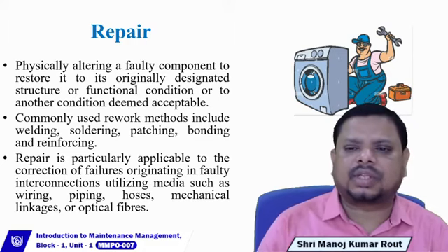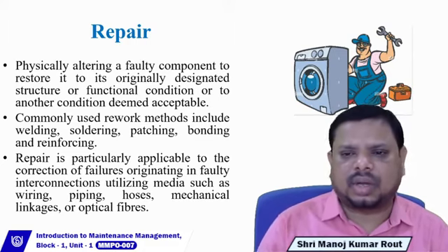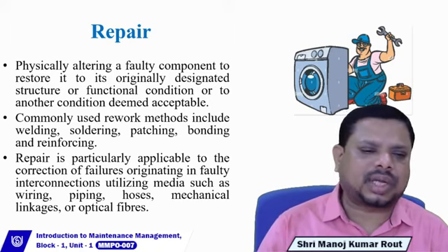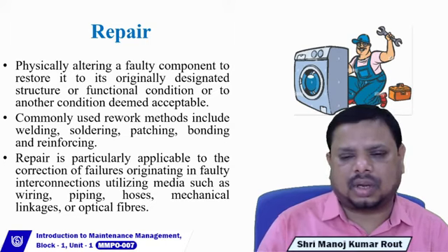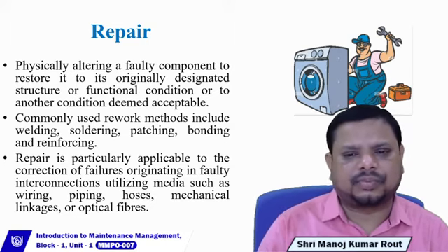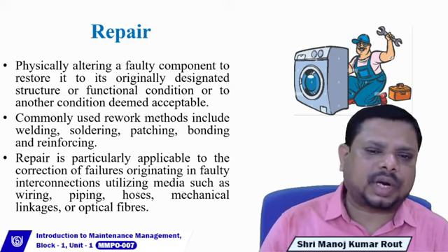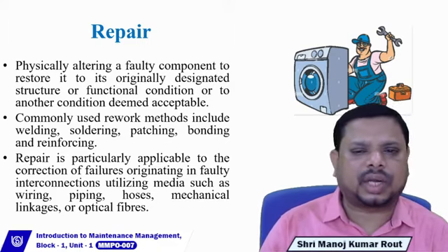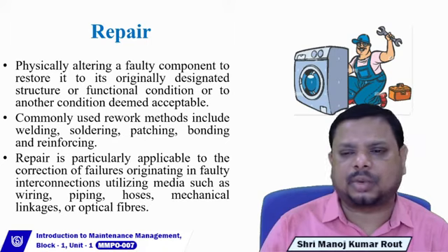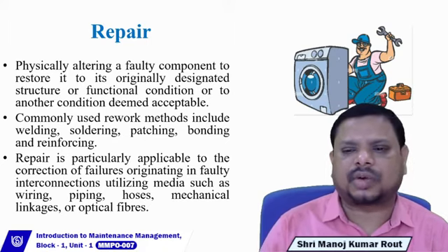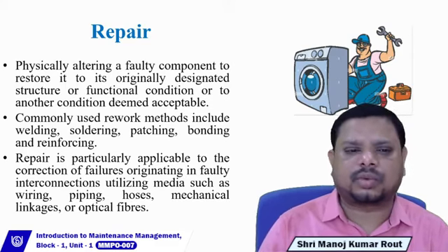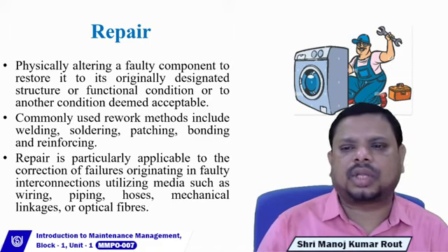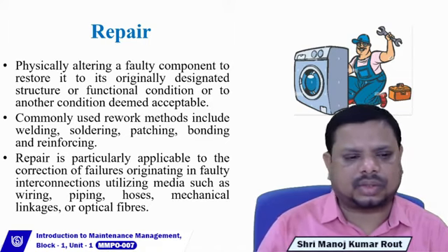So here I have given the example of washing machines, and in most cases the parts are made of plastics or reinforced plastics. So many movable parts are there. If required, you can directly go for repair by adhesive bonding. In some cases, you go for fiber welding. In some cases, with special reference to the electronic circuit of a washing machine, you must go for the soldering process.